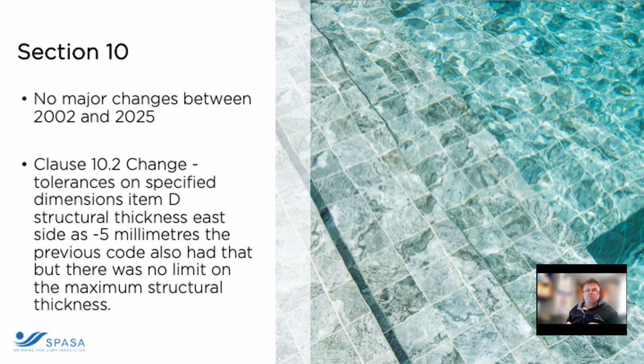It doesn't matter. So in other words, when you're putting your reinforcement in, if you've had to over excavate some areas for whatever reason, such as removal of a boulder, you don't have to put extra reinforcement in there. You're still putting your reinforcement in contact with the pull face. What happens behind is just excess cover, and the code allows for that.